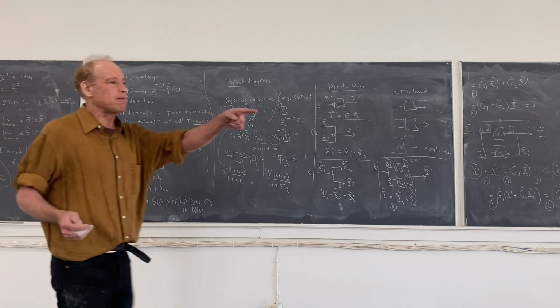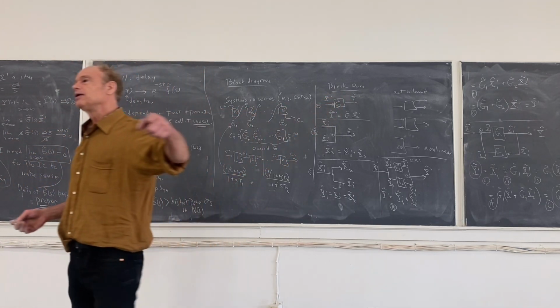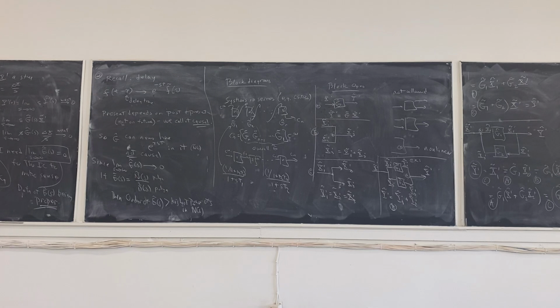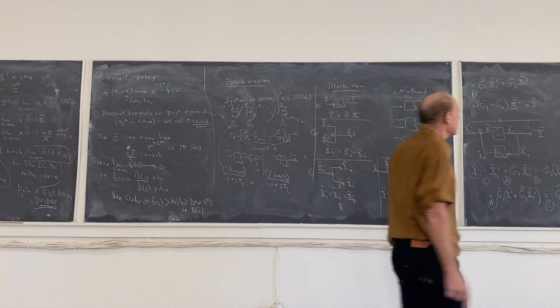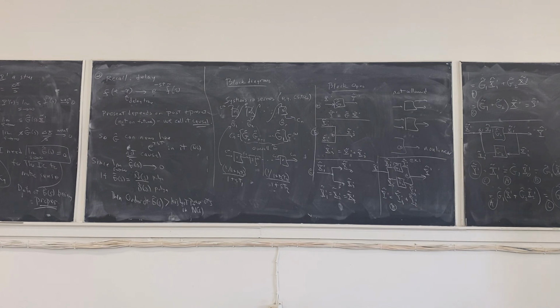Why don't we just build a pipe from here taking the hot stream, and instead of dumping it in the river, and instead of burning coal, let's put it through a heat exchanger with the stream going into a reactor over here and heat it up for free. Saves money, even if it's not a lot, it saves money. It also has the benefit of being good for the environment. Well, that's a feedback loop. Once you put a feedback loop in, and that's called heat integration, and now that's done in plants all over the place, every possible heat integration that you can do, you do for both energy savings and the environment.